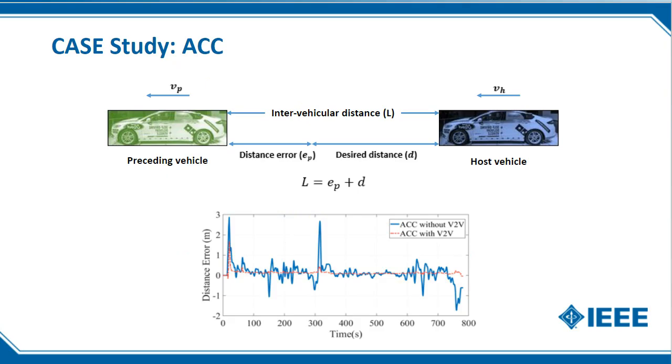Autonomous Cruise Control, also called Adaptive Cruise Control or ACC, is an example of Advanced Driver Assistance Systems or ADAS. According to the SAE International definition, these systems are considered level 1 autonomy. ACCs improve road throughput, safety, comfort, and the ecological performance of the vehicle. The intervehicular distance and relative speed of preceding vehicles are provided to the controller by a radar, camera, or another device. Using this information, the control system adjusts the vehicle's speed to follow the preceding vehicle smoothly at a safe distance. For our case study, an MPC-based ACC controller is designed and evaluated for a typical pickup truck.